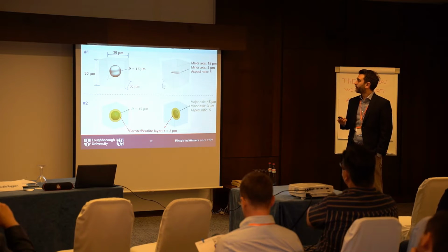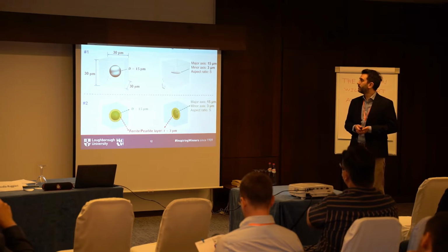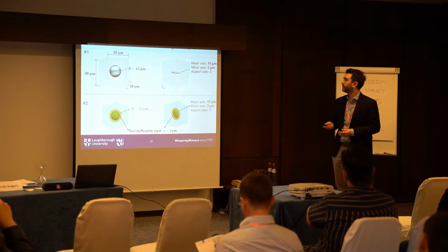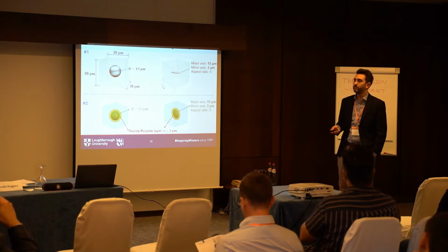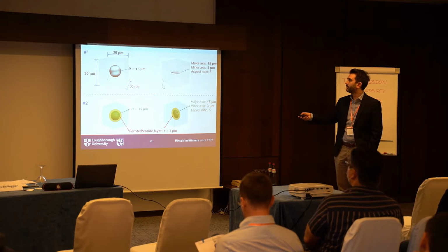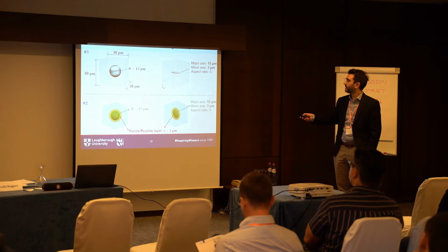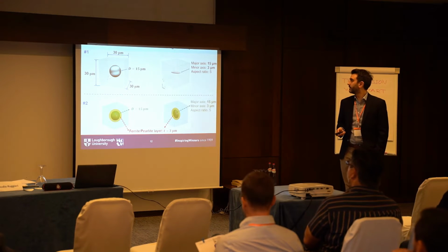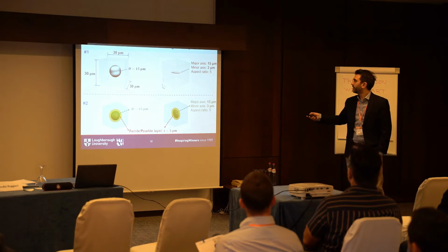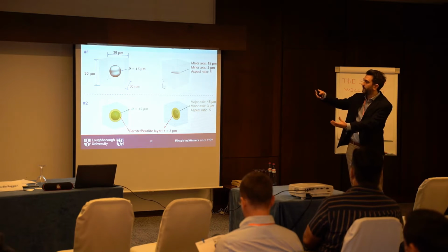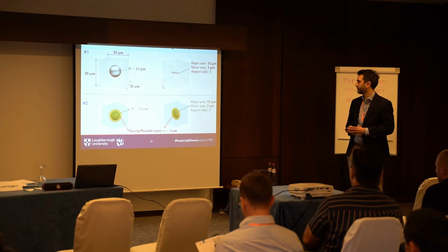Okay, if you have the statistical data, what you can do is homogenization approaches like the ones I showed earlier. So I'm going to talk about two different models here. The top one, you see a 30 by 30 by 30 cube, and then one spheroid of this diameter, 50 microns. And then we have, essentially, this is a vermicular one, the ellipsoid I mentioned earlier. This aspect ratio we have varied a lot, the angle we have varied a lot, you can find it along the diagonal, and so on and so forth.